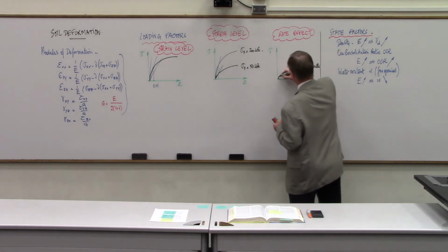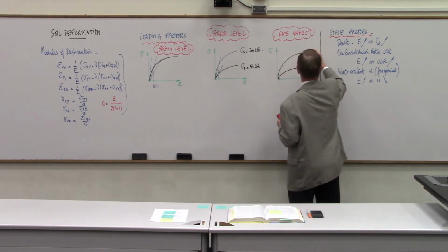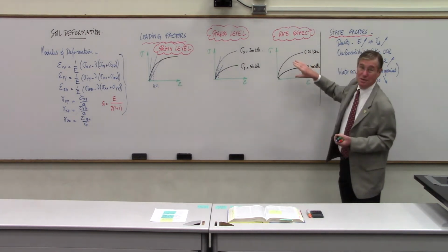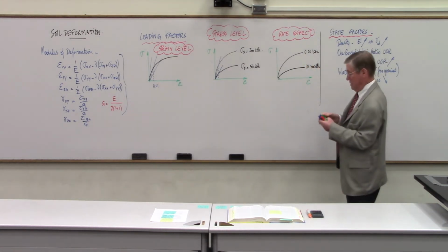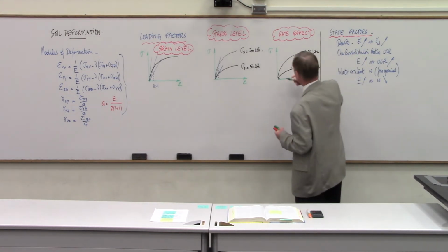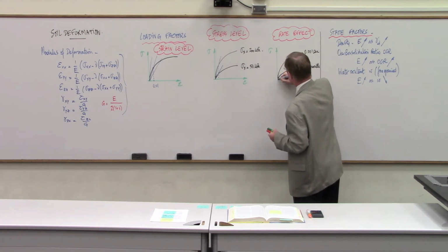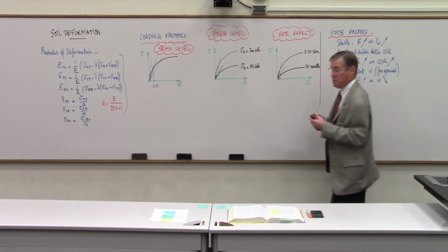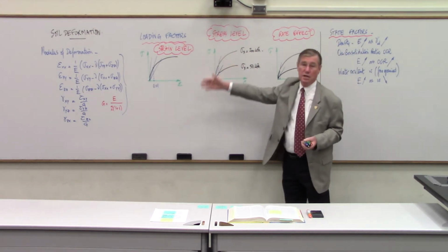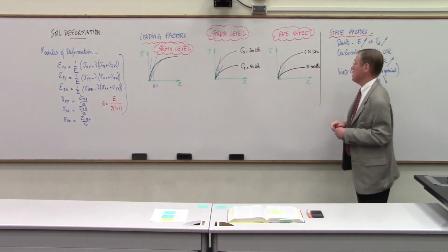And then, right here, I do another test, and I bring it to failure in 0.001 second. And boom! Well, you can imagine there's going to be a difference. And so if I'm going to take the modulus at 1% strain, then that's going to make a difference. Same soil, same confinement, same strain level, different rate of loading.